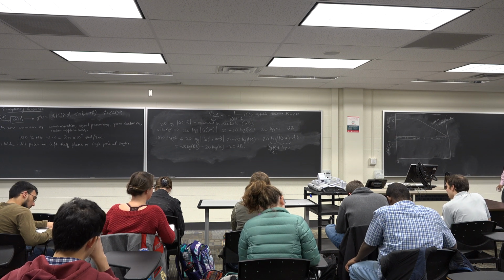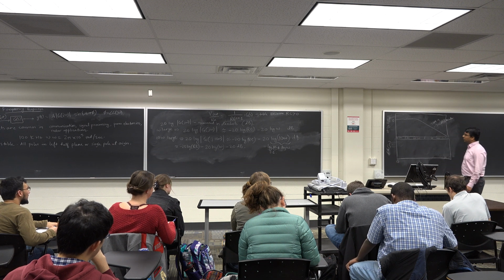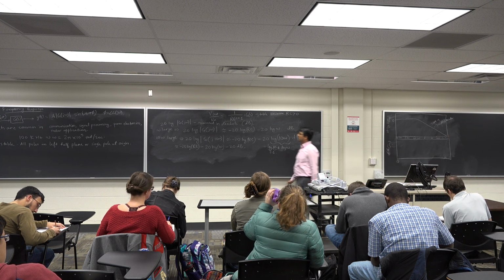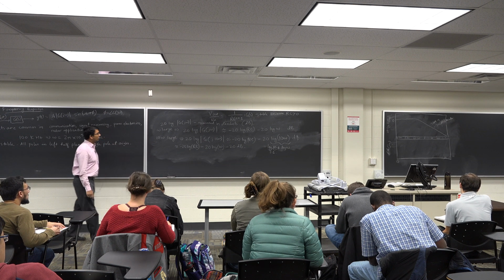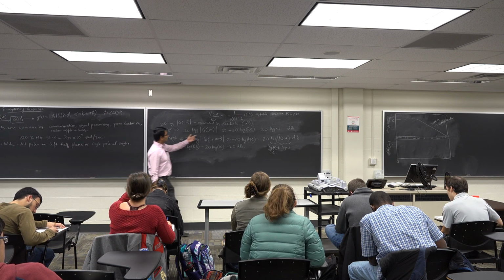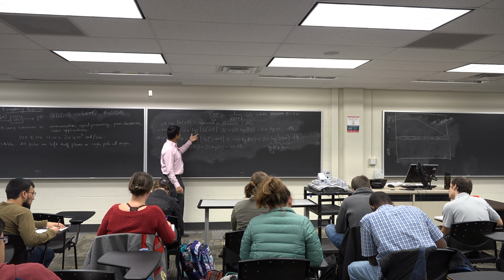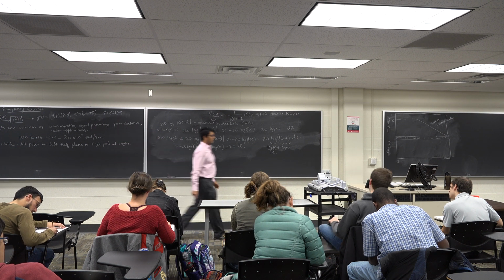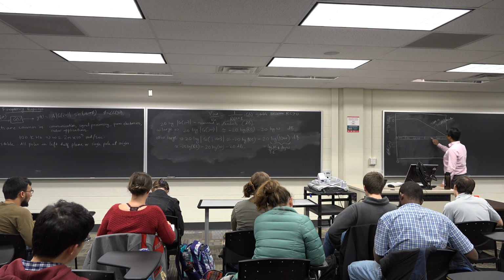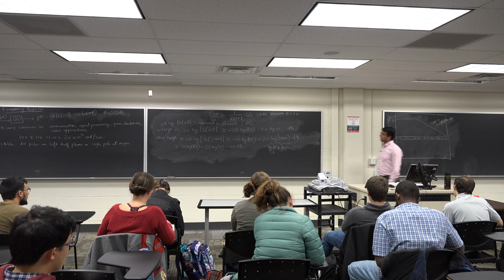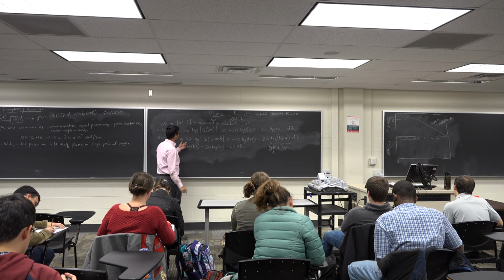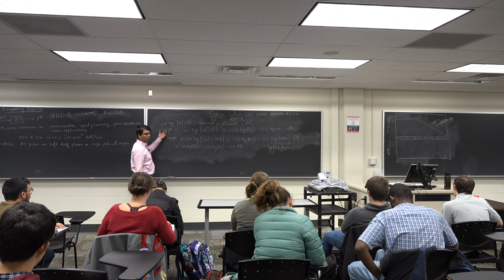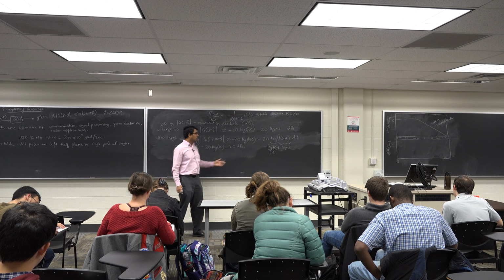We are going to stare at this equation for some time and then try and make sense of this particular graph. So if omega is large, my absolute value of 20 log absolute value of G(j omega) is given by this expression. If I multiply omega to 10 omega, remember that this is omega scale, so I'm going from 1 to 10 or 10 to 100. If I do that, I see that my value on the decibel scale is going to be the same as the value at G(j omega) minus 20 dB.